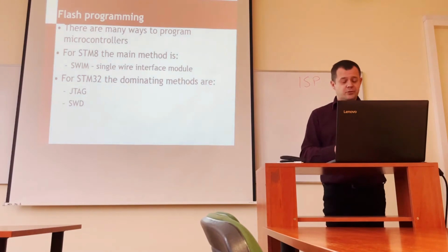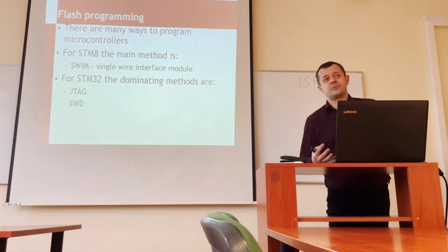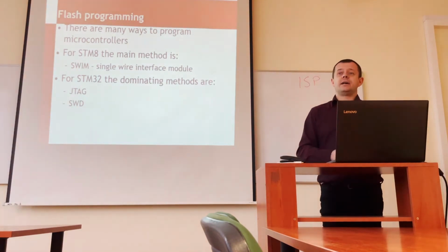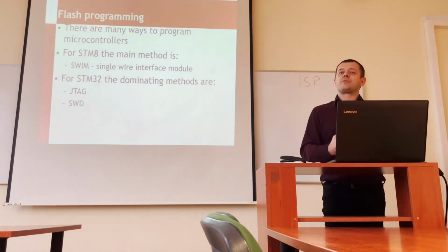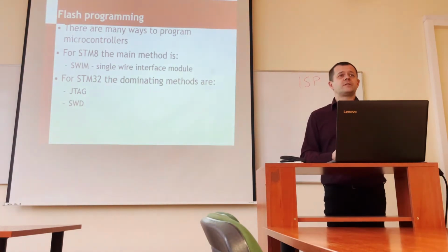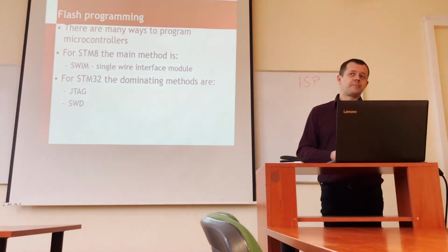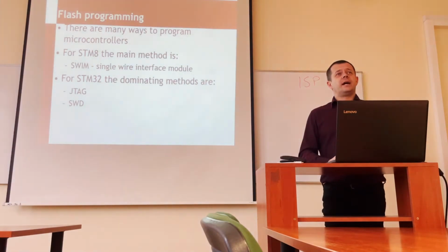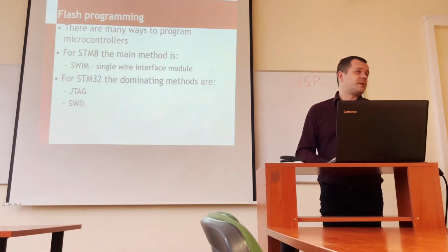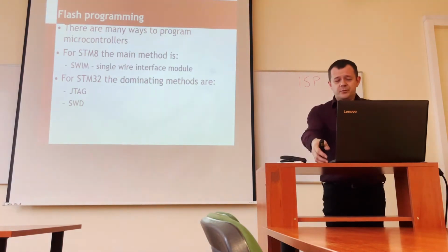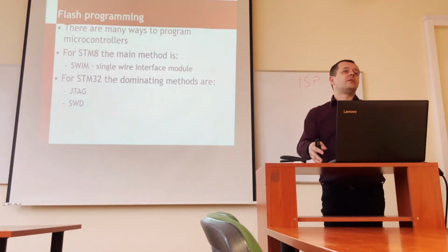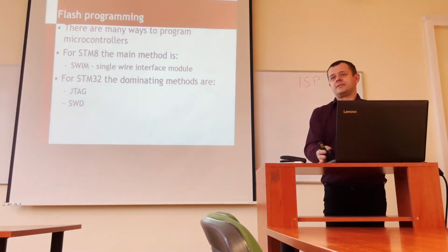One of the common solutions was the UART interface. UART was very popular, and 20 years ago, UART was the standard method of programming the microcontroller. The good thing about UART was that it was simple. It did not require almost any special setup, because computers 20 years ago all had a UART interface.